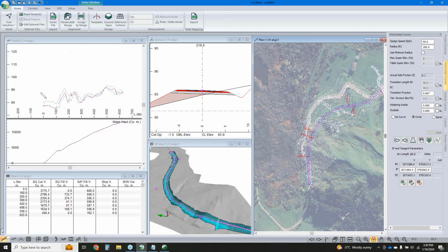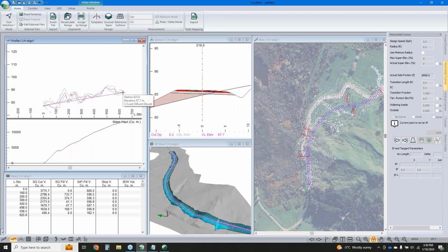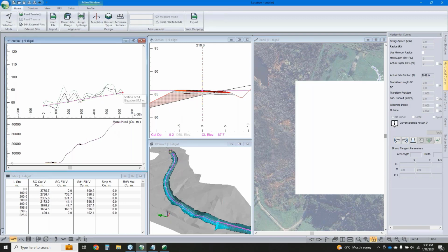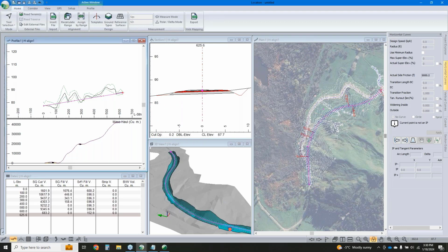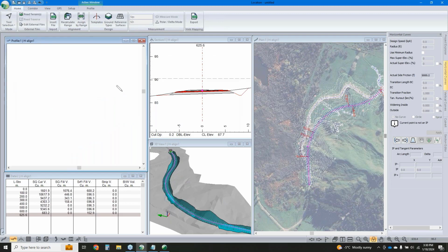And so this line in my profile is showing the cross section of the ground. We of course want our road to not have all those humps on it. So right now, if we do it as the straight shot, we're doing a lot of cutting. Our mass haul shows us that we're doing a lot of cutting.